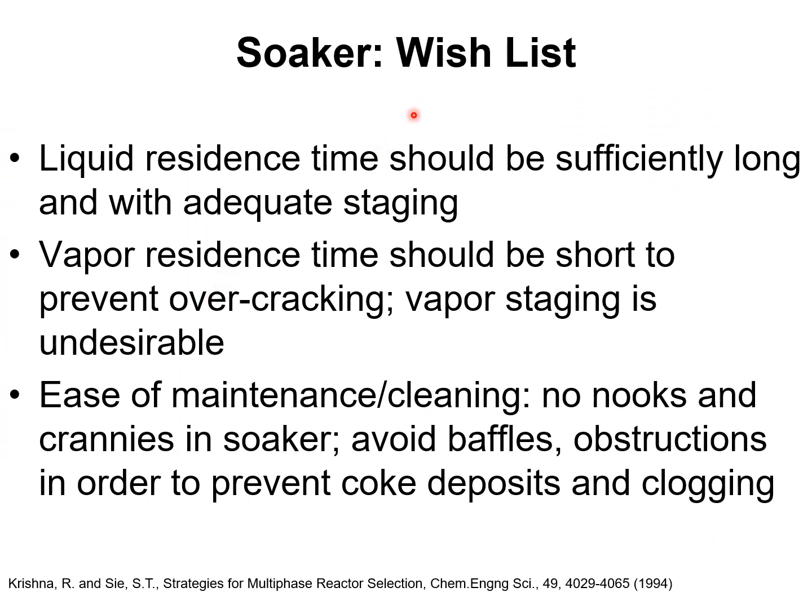Let's draw up a wish list for the configuration of the soaker vessel. We need to have an adequate amount of the liquid phase residence time, and the degree of back mixing in the liquid phase should be suppressed so that the residence time distribution is narrow, and overcracking is prevented.